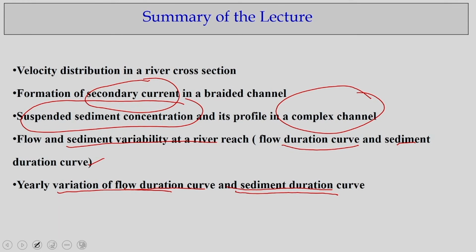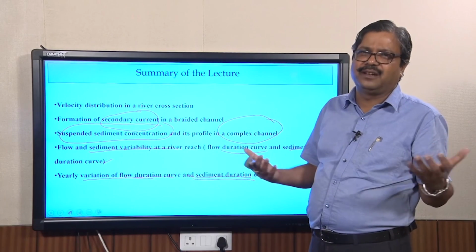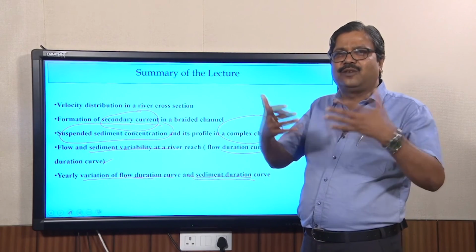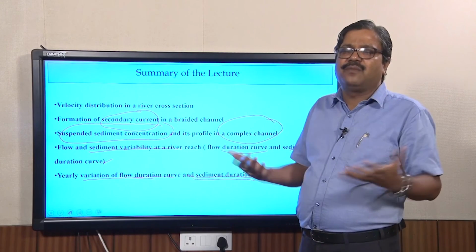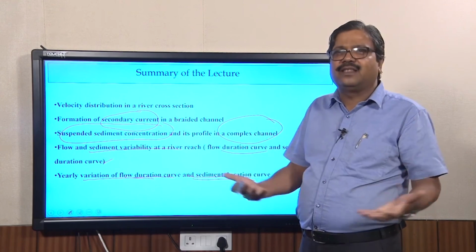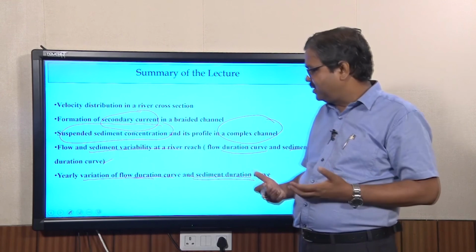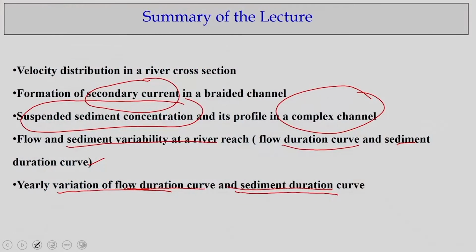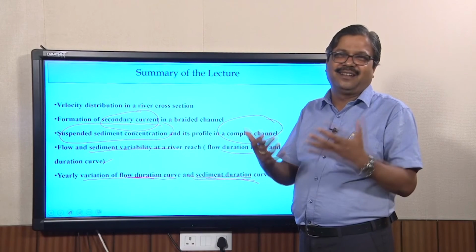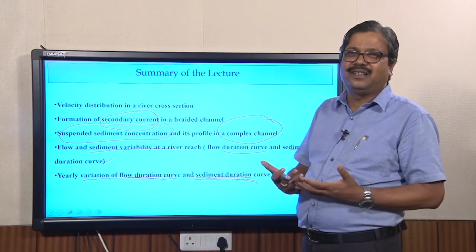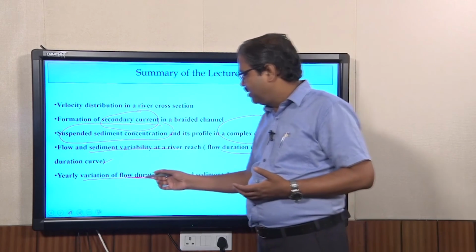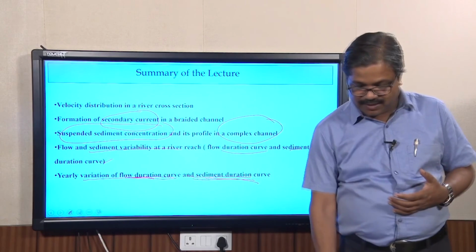The sediment and the flow duration curves show what response is happening at the catchment at that particular point, whether we are doing deforestation, whether a lot of dam structures are built, any anthropogenic effect is reflected in the flow duration curve and the sediment duration curve. As I said earlier, it is just like an X-ray of any disease, like a doctor needs. So, we also follow the flow duration curve and sediment duration curve.